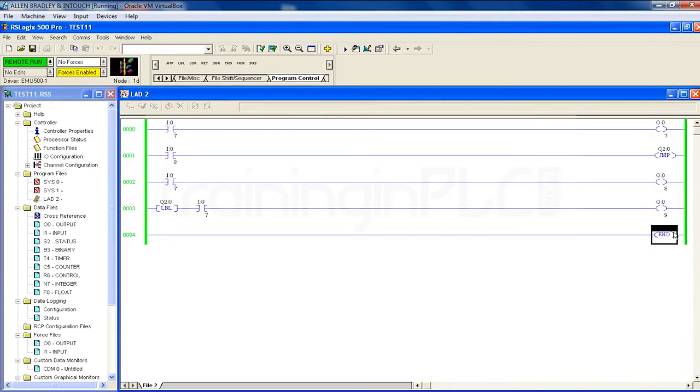So it will be skipping the rung. The rung limit is set by this label. This label I have introduced at the beginning of rung 3, so it will be taking before that. From here to here it is skipping. You can include 2 more rungs also here, no issues. So this is how you need to use the jump instruction. I'll show you one more example.